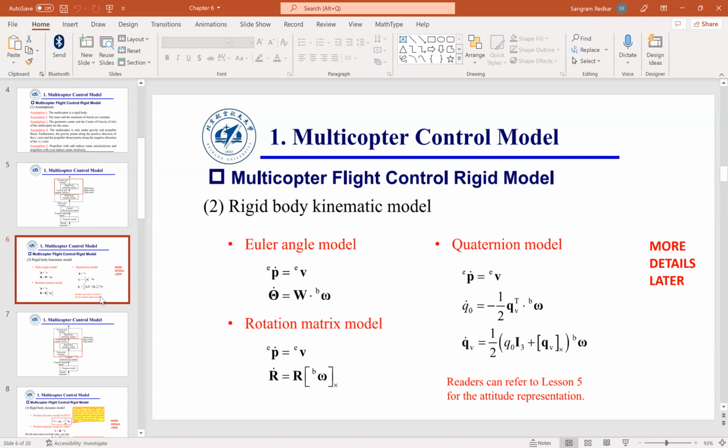So what I have done is I have written the Simulink code with the Euler angle implementation, and I have written the Simulink code for the quaternion implementation. I will share those Simulink files with you, and next time I will show you how the whole simulation runs. Equations are similar, but with quaternions, when you propagate, you have to normalize the quaternion every iteration. Okay, any other questions?